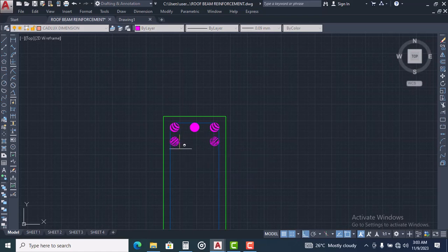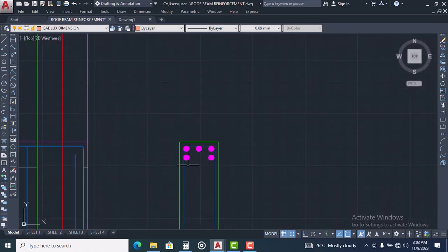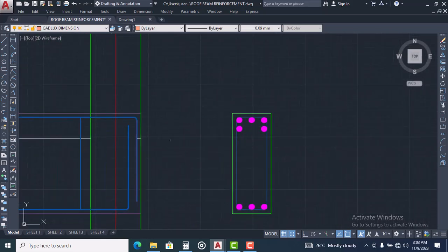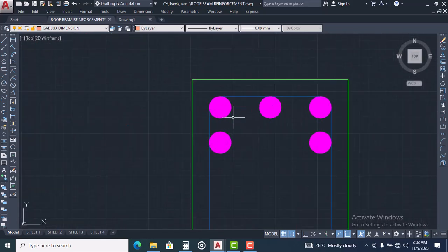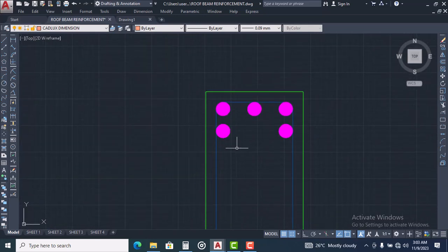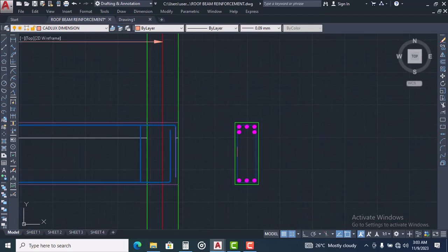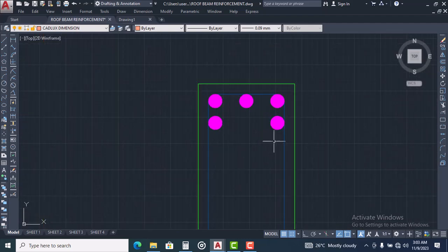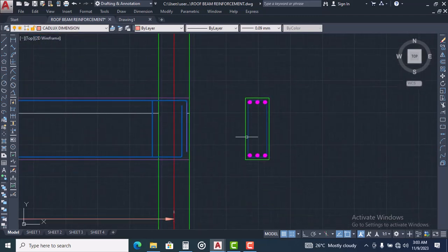So you can bring it down here and say 2, to specify that you have a double top reinforcement here. The number of 3 top wasn't sufficient for you, so you have to provide another reinforcement here. This depends on the structural analysis result. We'll still get there, but for now let's just stick to this section A.